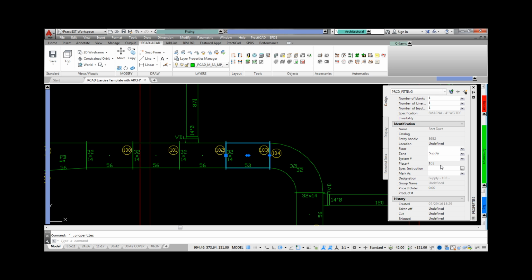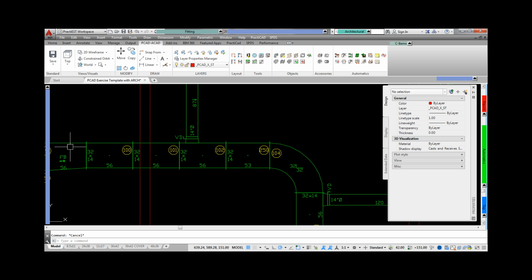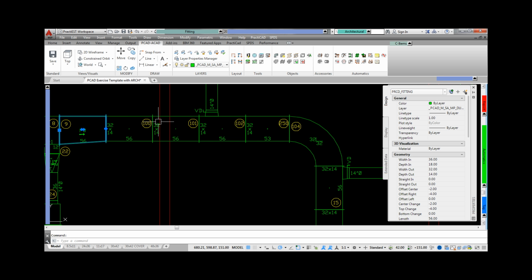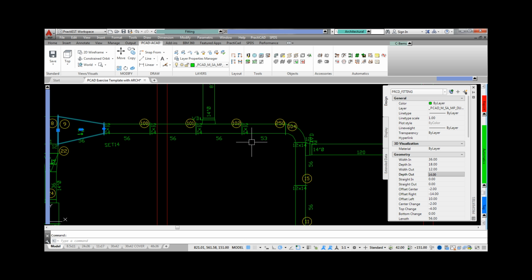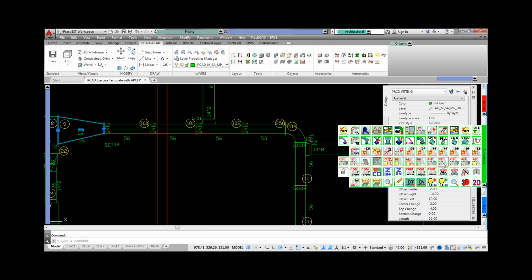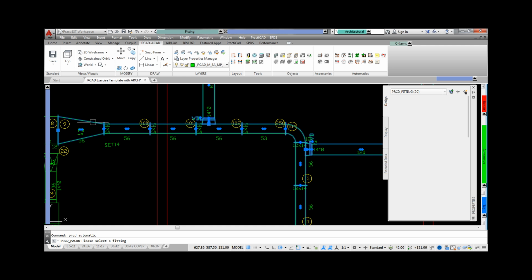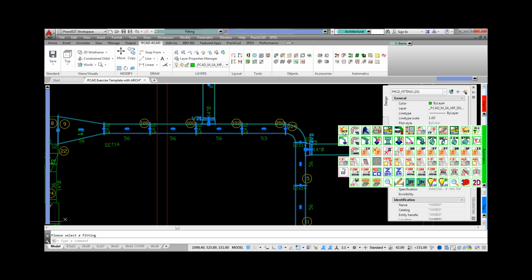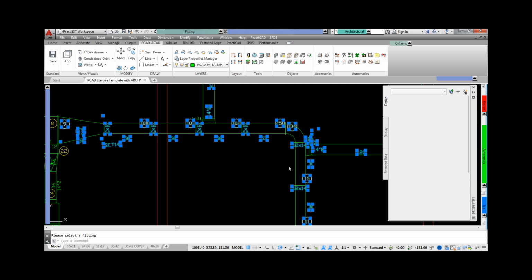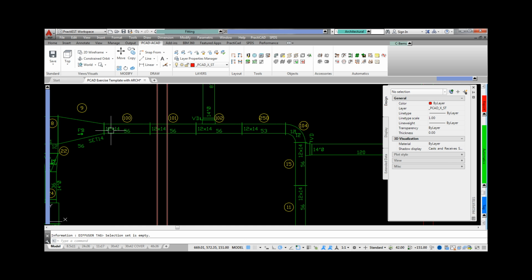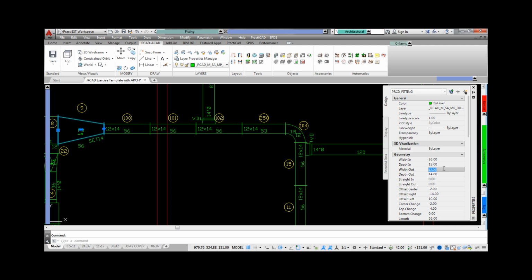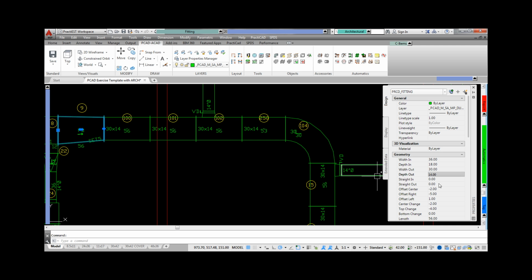And of course, things can be edited individually and from a lot of different areas in the software. See here as we simply click on a fitting and change a piece number right inside the AutoCAD property box. Now we're going to make a drastic edit of the parameters of this duct line. Notice now that the tags and the piece numbers don't sit where they should. The drawing is no longer neat and clean. We'll just use one automatic to select duct line forward and use another one to retag, and everything is back exactly where it should be. And yes, this video is showing these changes in real time. Finally, we're going to edit things back the way they were. Once again, all happening in a simple mouse click.